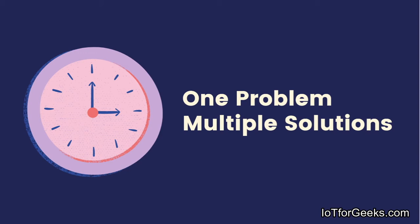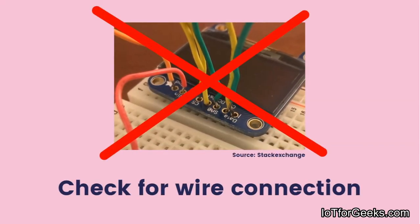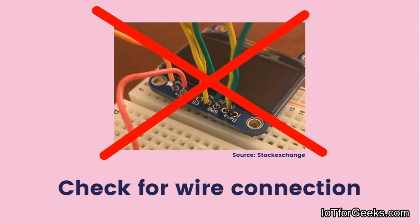up. You try a lot of different things but no luck, then you are at the right place. Whether you interface the OLED with Arduino, NodeMCU or any other board, there are some common checks you should do before thinking your OLED is dead. The first and foremost check to do is the pin connection. Yes, if there is no proper connection between the OLED display and your microcontroller board, then your OLED display will not show any output. Okay, so it should be properly soldered.